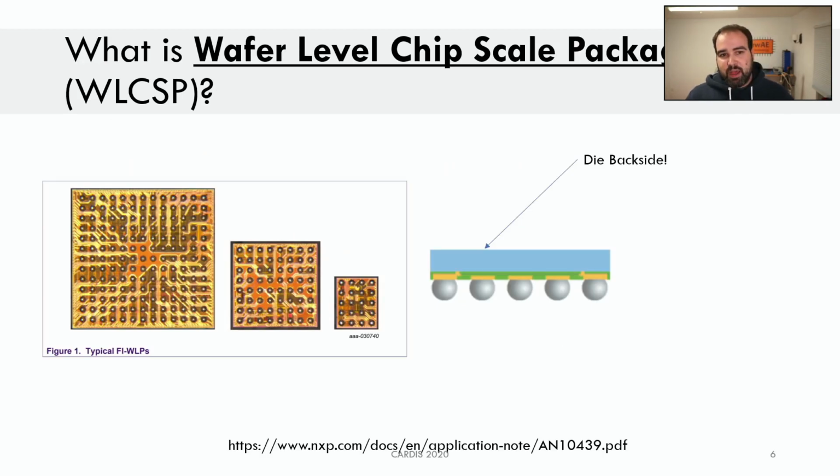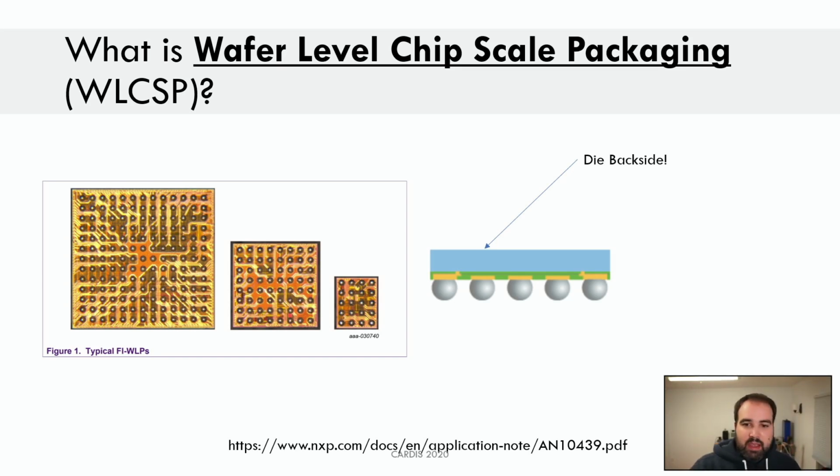So to bypass the requirement to expose the die, what I looked at is using Wafer-Level Chip-Scale Packaging, or WLCSP. This has been shown before. There are several examples of this being used for BBI even, but I didn't see it used in a setting that was actually investigating how well you could apply it and what it meant for the attacker or defender.